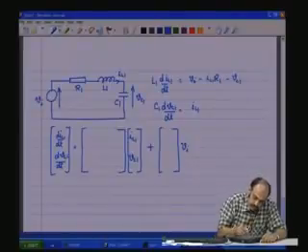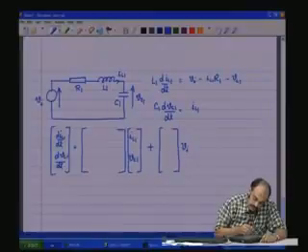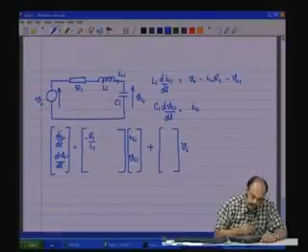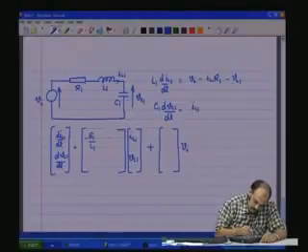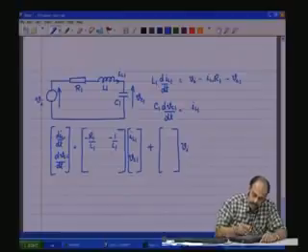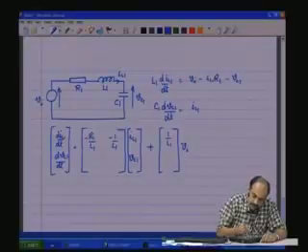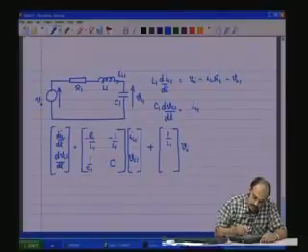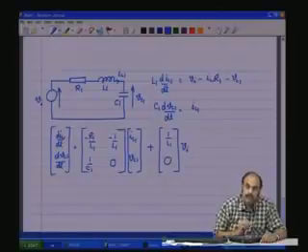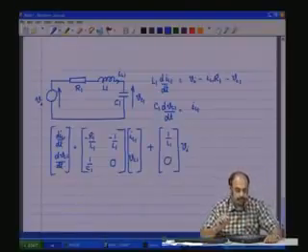Now, look at the equation here, there is a minus R1 by L1 coming to the picture. Now, there is a VC1 which is minus 1 by L1, and 1 by L1 for the B matrix, that is VI. Now, the other equation, we see that there is a 1 by C1, there is nothing here and nothing here. So, this is the dynamic equation.